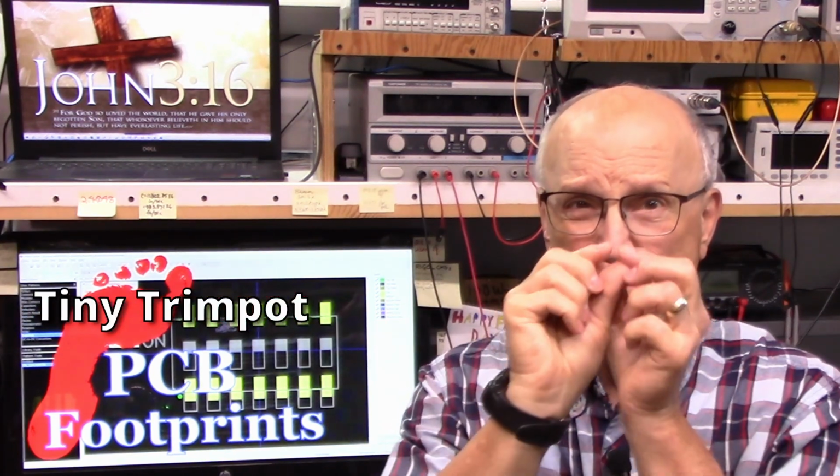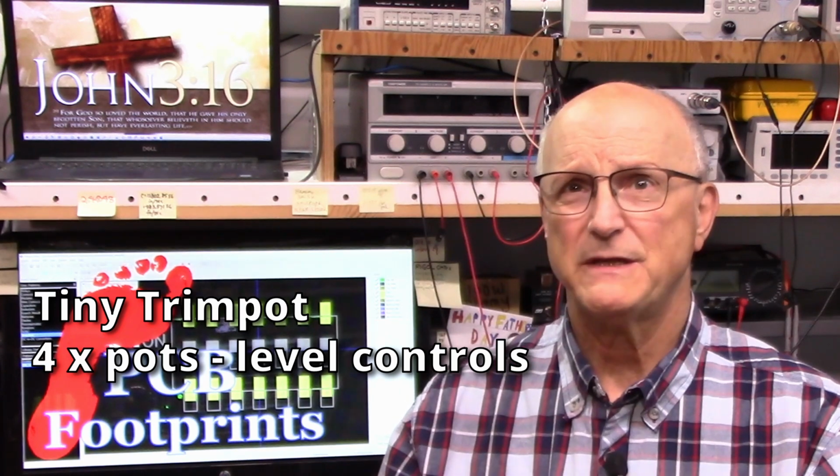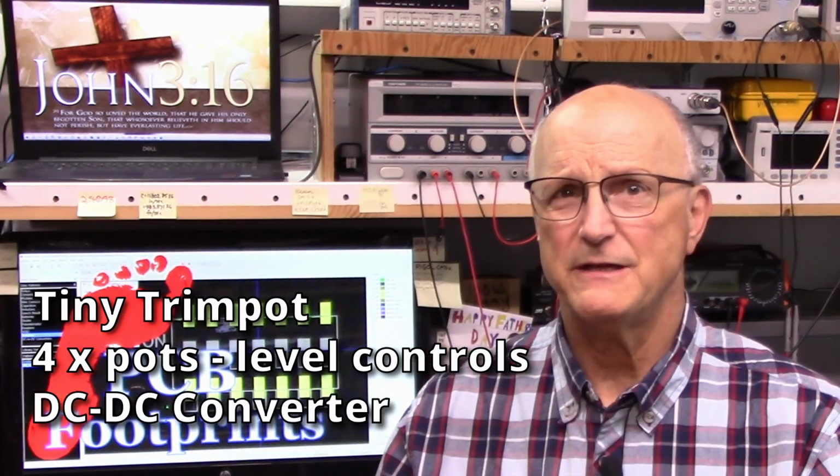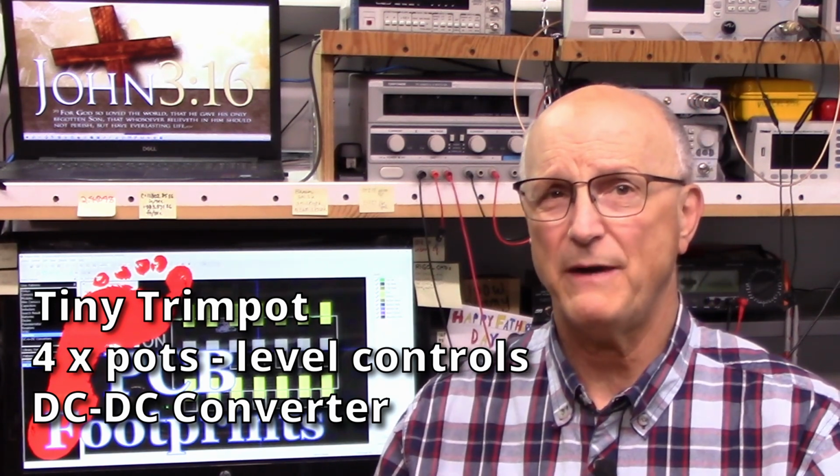There is the itsy bitsy teeny weeny little potentiometer used to adjust the LED trip point for the output level indicator. There are all of the level potentiometers. There are 4 of those. And then finally the DC to DC converter that I chose for the power supply. Now, I'm not going to go through the whole process of creating all 3 of these footprints in this video. I will choose the DC to DC converter as a representative device and create its footprint in detail for you.